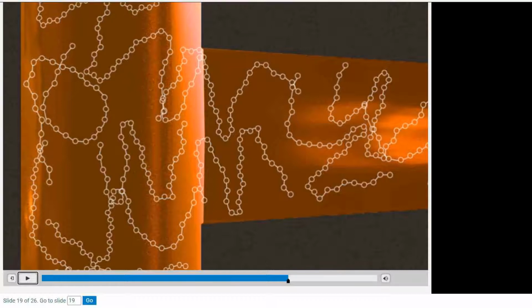Okay, and then these molecules are made to flow. They are flowing, they're aligning themselves in the direction of flow. And as soon as the material stops flowing, these molecules go back to a coil formation, as we call it. They want to tangle up again. And if you freeze the material in while it's flowing, which we call flow-induced stresses, then there is potentially a problem. With flow-induced stresses, the molecules don't want to be frozen in, aligned, and therefore you may have trouble with molded-in stress.